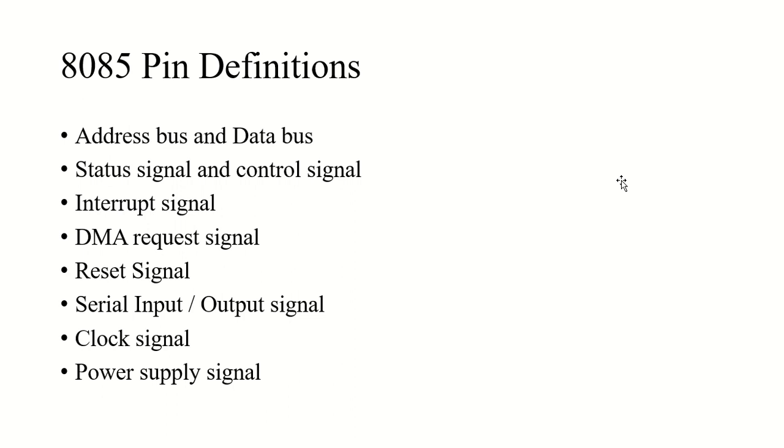Okay, so if you are thinking about, oh, can't I use 4 bits for address and 4 bits for data? No, you cannot do that, right? So ALE works as a demultiplexer, and it is a latched control signal. Then we have IO/M, which is an output status signal which is used to give the information of the operation to be performed with the memory or input output devices.